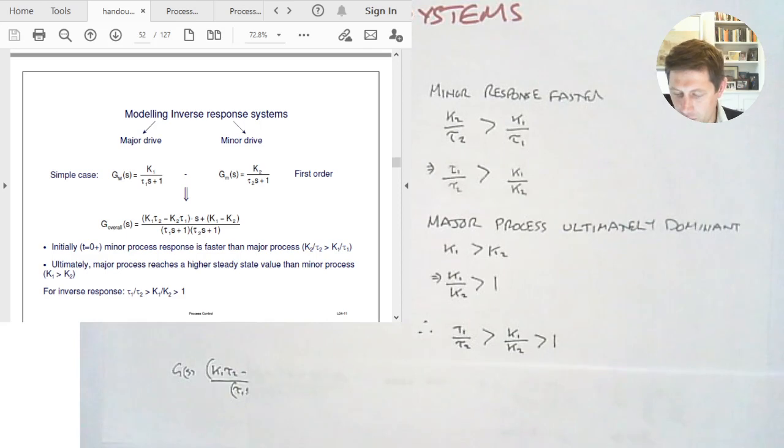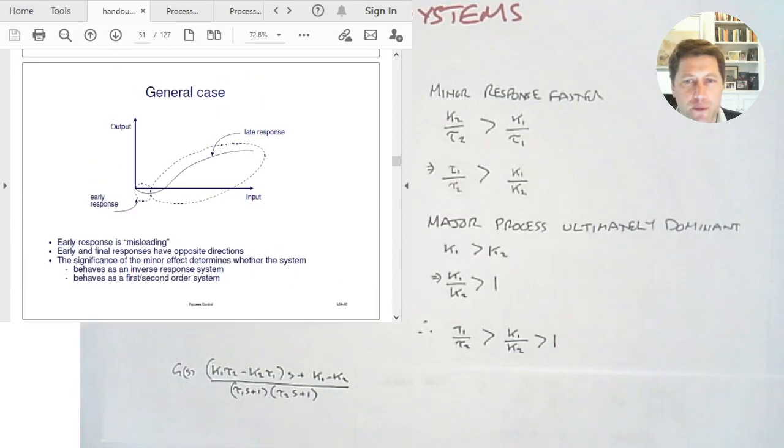And we can also look at what that means. We had an observation a moment ago that the transfer function was interesting because it passes through the axis here. So we know that the response, ultimately, for example, when it reaches a steady state, we know that the output response is equal to the steady state gain multiplied by the magnitude of the input step function, if that's the input.